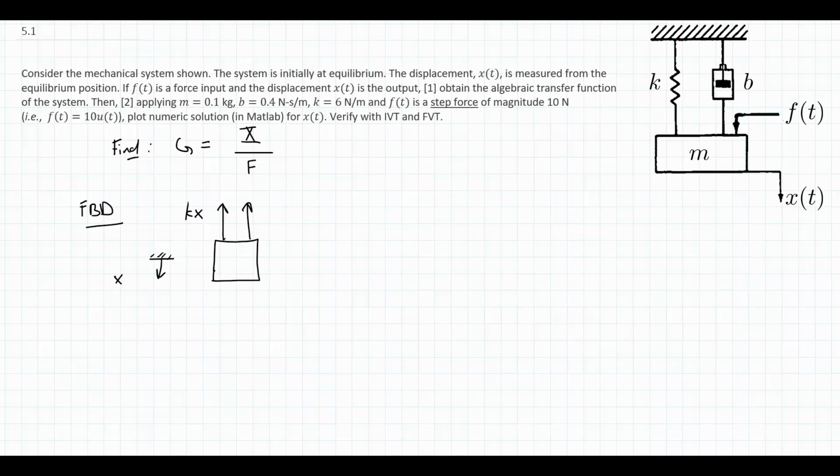Moving on to the damper, same idea here. The top of it is attached to the ceiling and the bottom of it to the mass, so the ceiling part cannot move, so the tension or compression of the damper is completely determined by the velocity x dot of the mass. So again here, will a positive or a negative velocity cause the damper to be in tension? A positive velocity means that the mass is traveling downward, stretching the damper apart, and thus putting it into tension.